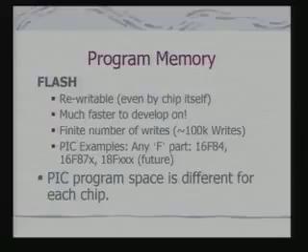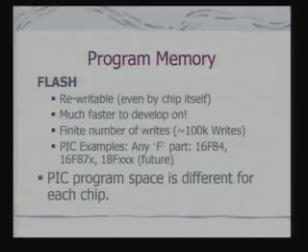The other option is flash. You can have flash in the program memory as well, and when you have flash, the PIC nomenclature typically has an F. Flash is an electrically rewritable memory, and it can be written even in circuit and is much faster to develop on. Why?